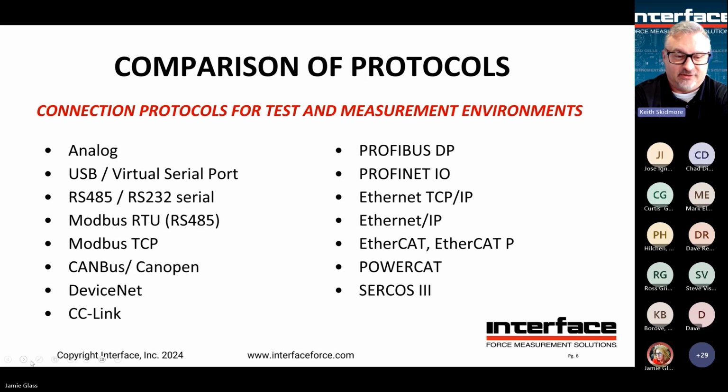Modbus RTU is basically Modbus over RS-485. There's also Modbus TCP, which is over the standard Ethernet protocol. Got CAN bus, CANopen, DeviceNet, CC-Link, Profibus, Profinet, Ethernet TCP/IP, EtherNet/IP, EtherCAT, EtherCAT-P, and you've got POWERLINK, SERCOS, and the list goes on.